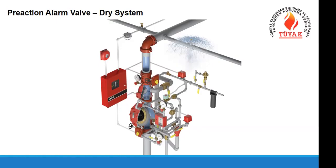So it should be a pre-action system. When a sprinkler breaks accidentally, the system gives you an alarm that there is a problem, a sprinkler open, but the detector doesn't give us a smoke alarm, so there is no fire. So in order to be a fire, two actions are needed. So this is called pre-action alarm valves.